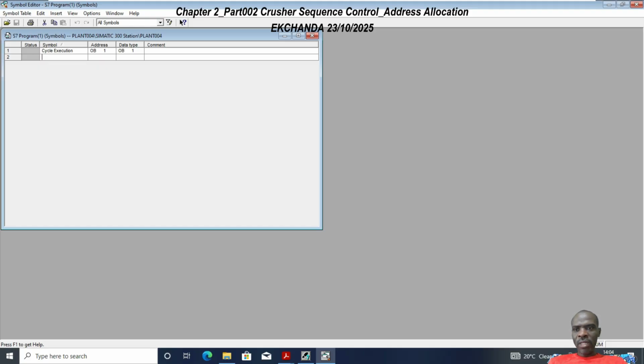So this first Boolean input, I'm just going to call X1, and I want this to be a Boolean data type, with first address memory bit 9.0. And then for a timer, I'm going to just call T100, and then this is going to be T9, because all the inputs and the timers usually just start from 10.